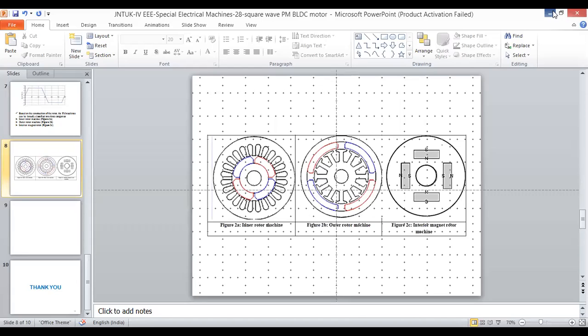If you consider a three-phase machine with three windings shifted in space by electrical 120 degrees between them, it produces a rotating magnetic field constant in magnitude and traveling at an angular frequency of the currents.